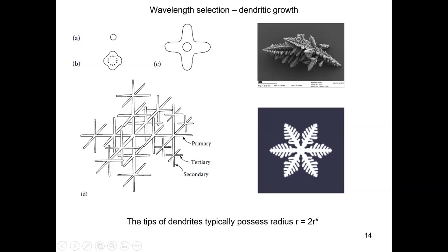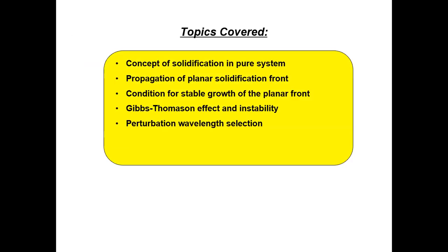And then you also know the relation from the critical radius to the theoretical supercooling. So this basically tells you that every snowflake, or every small solid pattern that you see here, has imprints of the thermodynamics, the temperature imposed to induce solidification. And this is through the Gibbs-Thomson effect. Okay, so this is a very cool thing that I just wanted to quickly mention. With that, I think that's all I want to tell you about the solidification of a pure system.